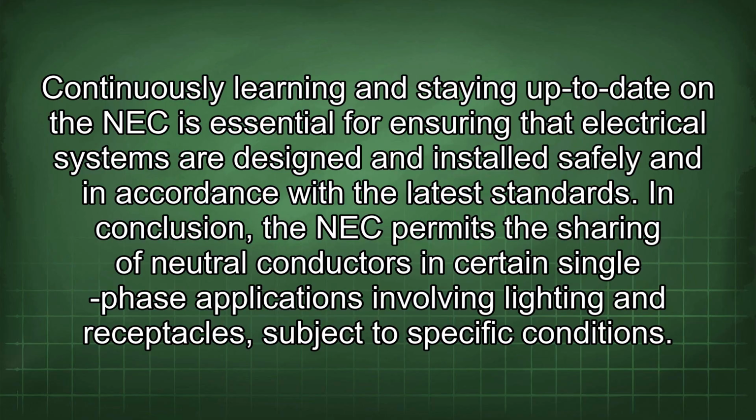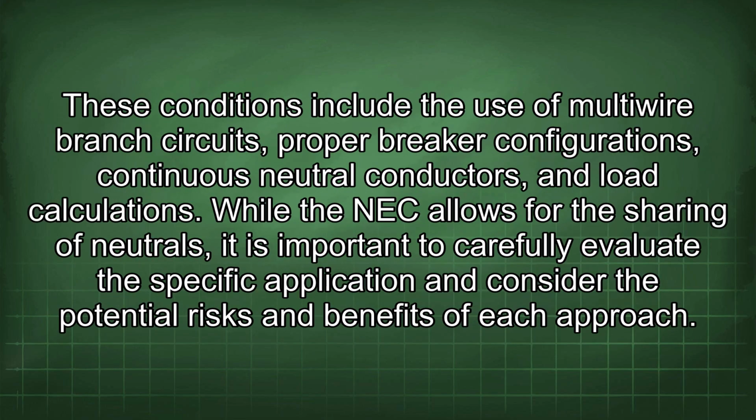In conclusion, the NEC permits the sharing of neutral conductors in certain single-phase applications involving lighting and receptacles, subject to specific conditions. These conditions include the use of multi-wire branch circuits, proper breaker configurations, continuous neutral conductors, and load calculations. While the NEC allows for the sharing of neutrals, it is important to carefully evaluate the specific application and consider the potential risks and benefits of each approach.